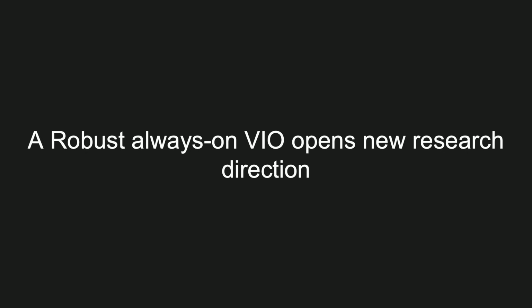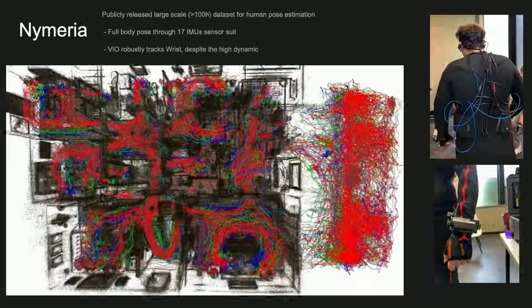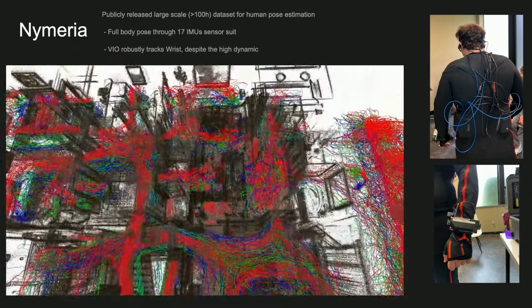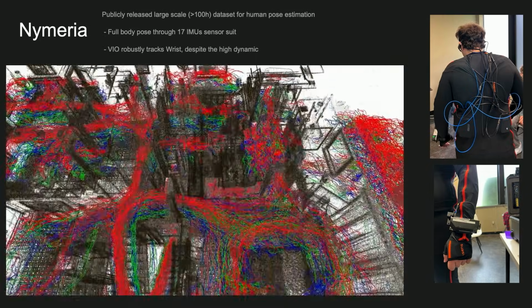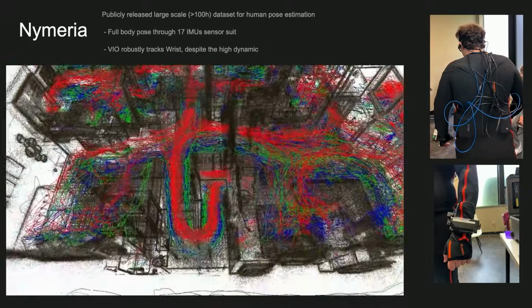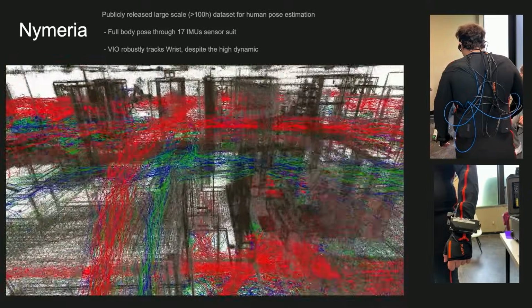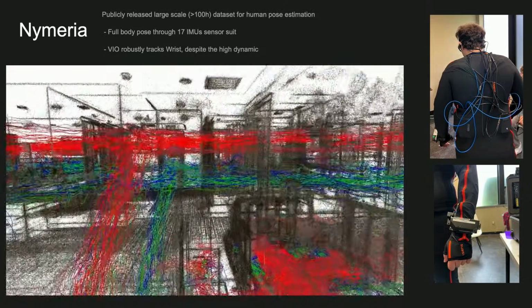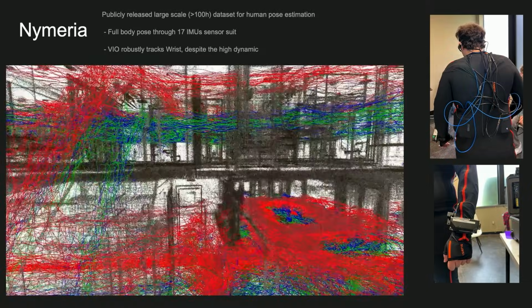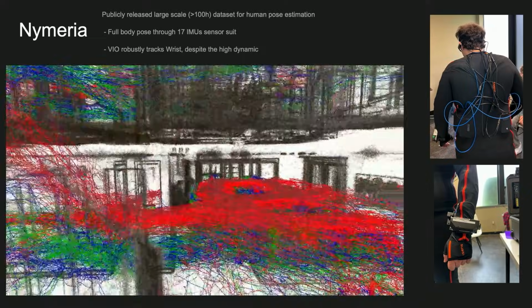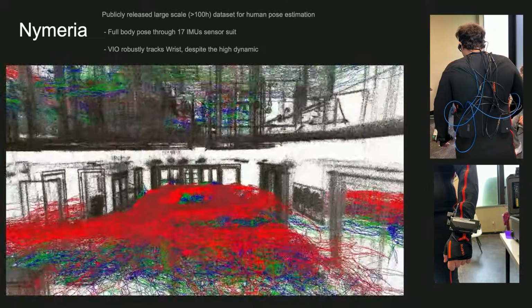So that's kind of interesting, but what can we do with an odometry that is as good as this VIO? That actually opened quite a lot of research directions. Jakob talked about the LaMAria dataset. The fact that we did the temporal modeling right is the reason why we can actually track the motion of wrist. Wrist is going to be way, way higher in terms of dynamics than 300 degrees a second. So if you have any timestamping error here, you will lose track quite easily.